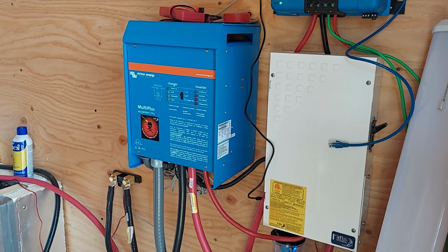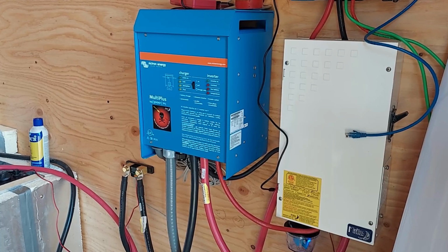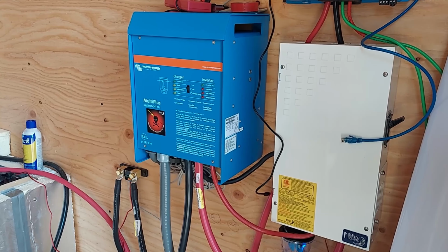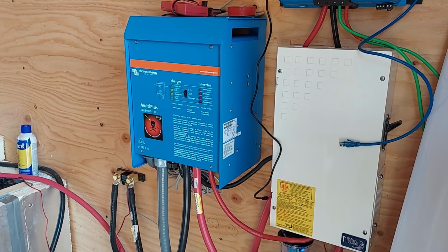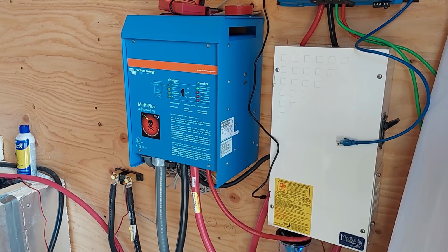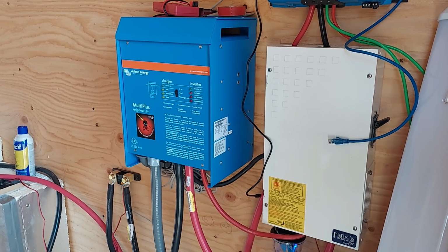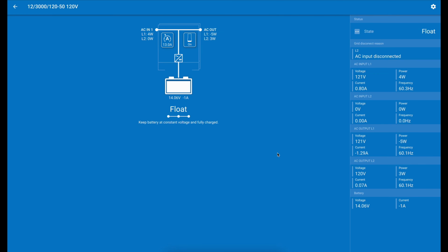On most Victron inverter systems, once there is AC power present, you will see the mains on light blinking. This indicates that while there is power, the inverter is either qualifying or the power is outside of its accepted range. If you have a generator no connection condition, then the next step here is to jump into Victron Connect and see what the inverter sees.